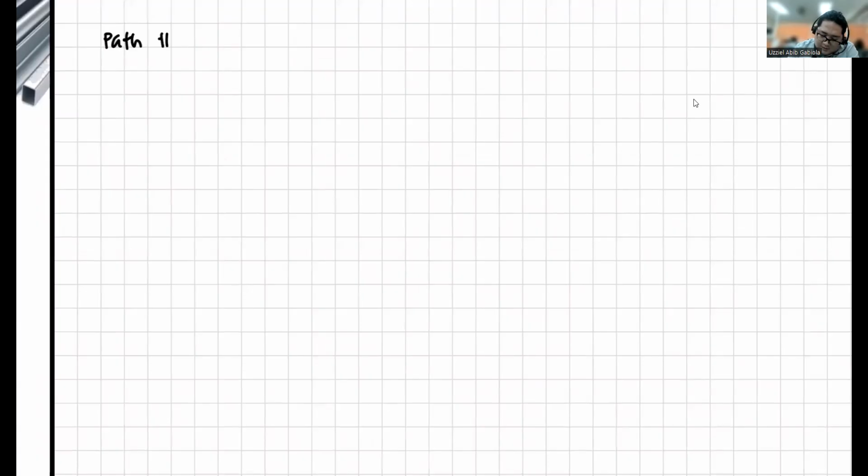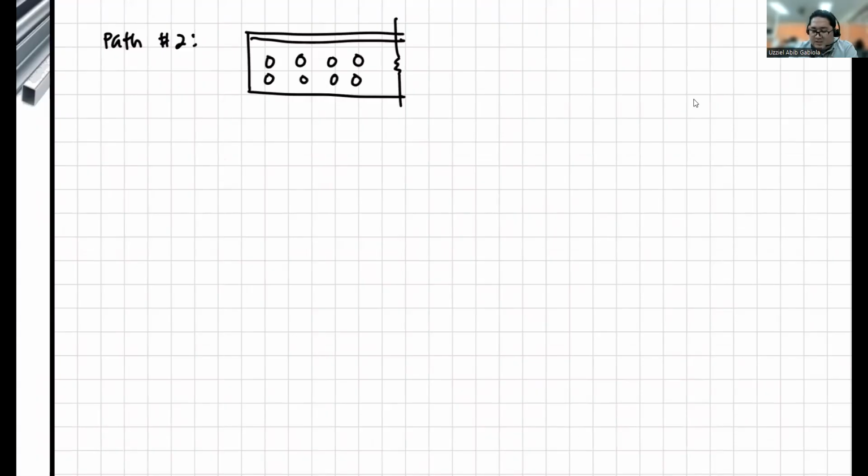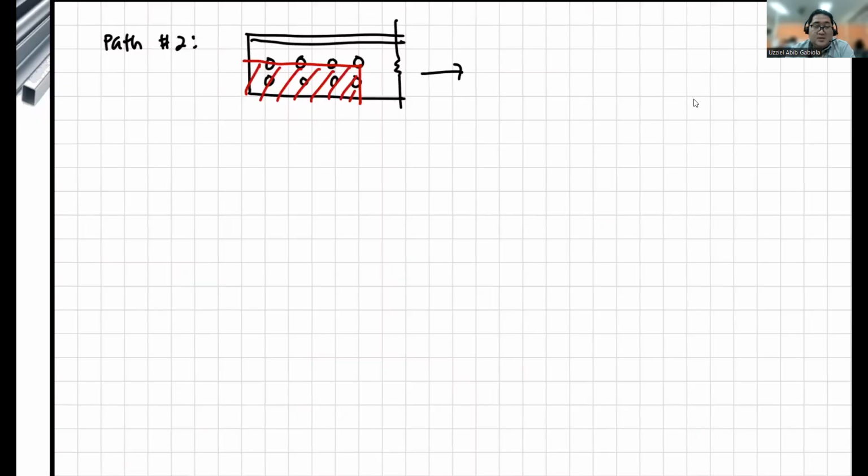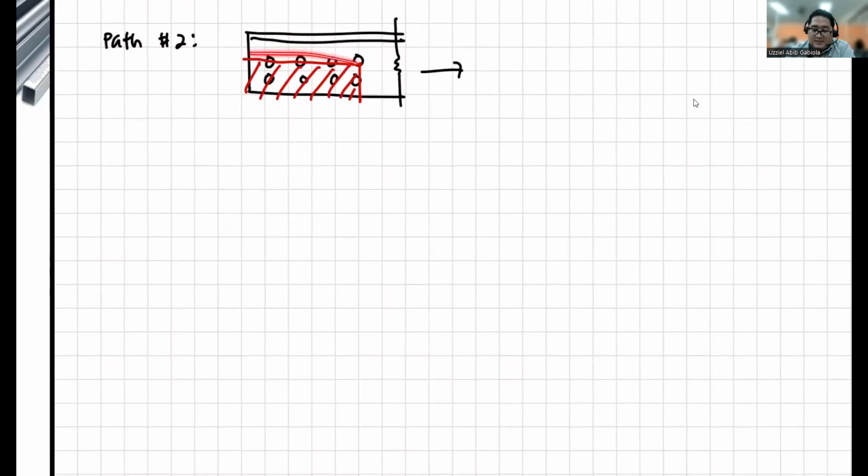Our path 2 looks like this, this is our L connection, these are our bolts. What happens now is the shear plane and then straight down. This is the block that will be left. This is our applied loading. So what changes? We have here the same shear plane, same distance. The only thing that changes now is our tension plane. It gained additional area at the bottom.